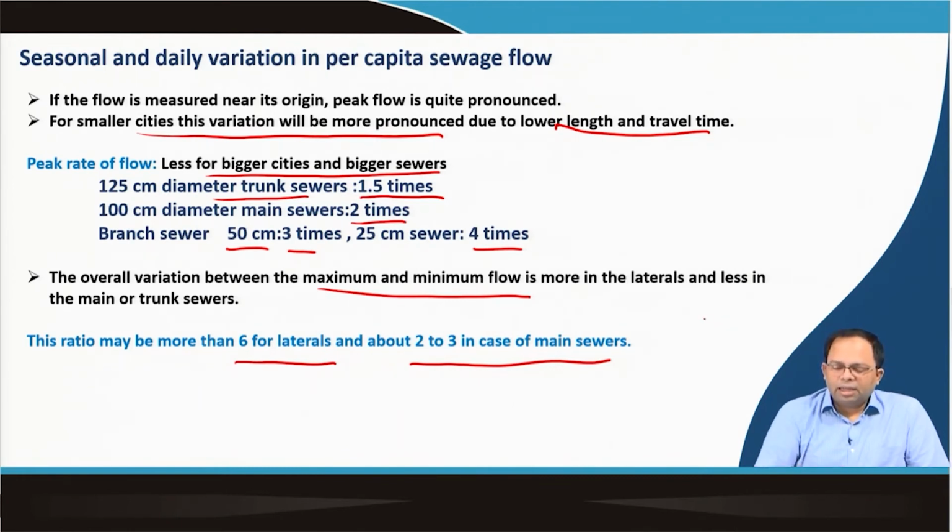Now, as you can understand, if I have a circular sewer, sometimes it would be flowing like this, sometimes it would be flowing like this, or like this. So, we have to think about, if flow is like this, different problems arise. If the flow is almost filled up, then other problems arise. So, we have to design our pipeline considering both the extremes of this kind of flows.